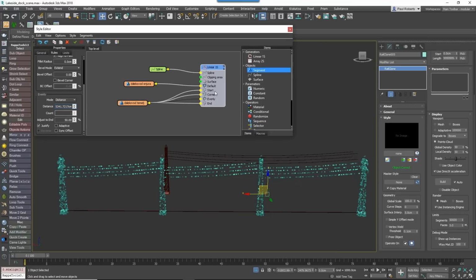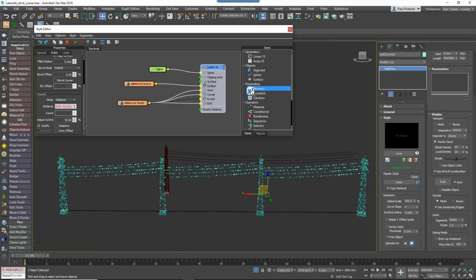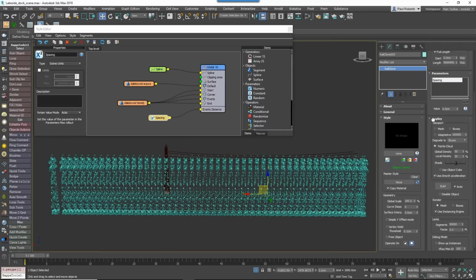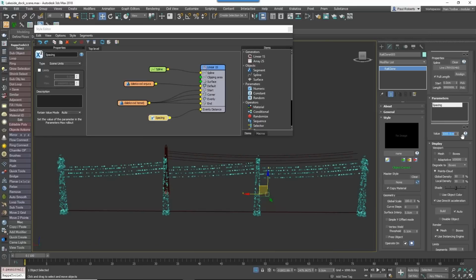It's not always the easiest thing to open this graph and change that. So one thing you can do in RailClone is to export any property, like this evenly distance property, and wire it to a numeric node. Any numeric node in the scene, and I'll just give it a name so we can see what it is, but any numeric node in the scene ends up in the modify panel. And that means that you can change this property without ever having to open or understand this graph. Like so.